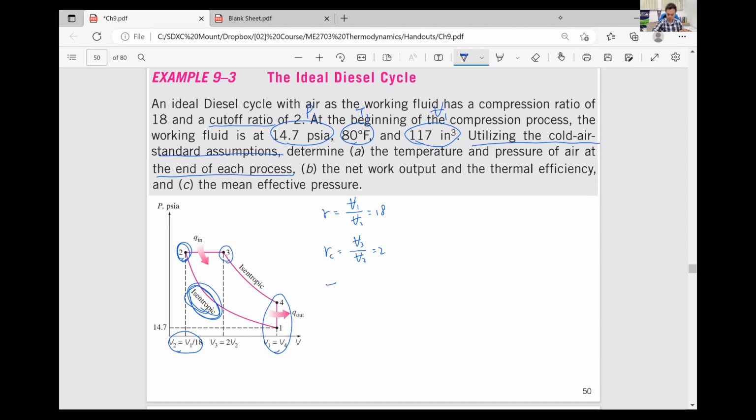So it's an ideal gas undergoing an isentropic process, with constant specific heat. We know there are three very useful equations to use, right? T V to the K minus 1 is constant. So T1 V1 to the K minus 1 equals T2 V2 to the K minus 1.